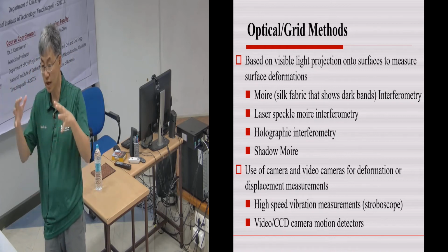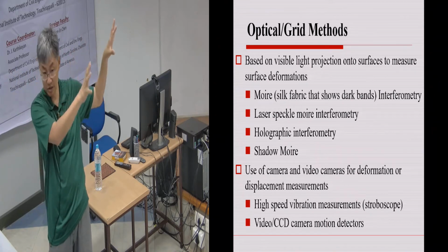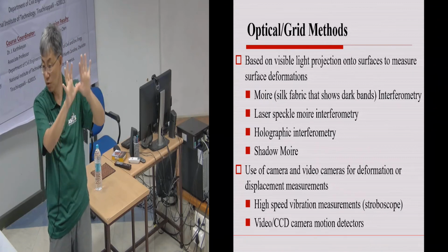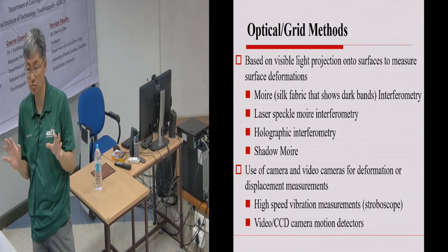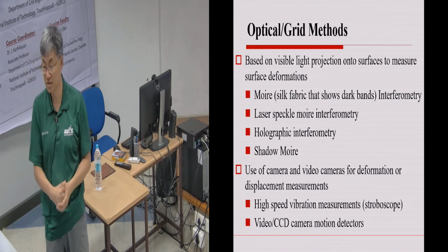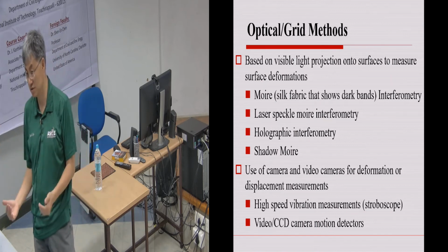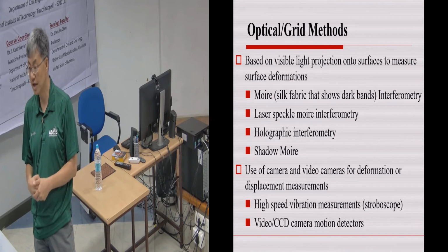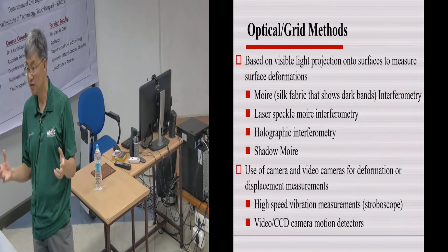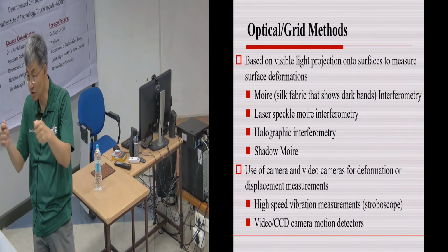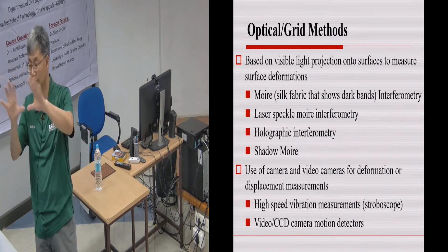Hologram is you create an artificial surface on a material, and then when the material starts changing, the hologram will be able to pinpoint what are those changes. All of these are deformation based, okay. But deformation is extremely important, right? Because as we discussed yesterday, we never measure force or stress. The only thing we measure in real life is deformation, okay. And optical methods also have another area of benefit, that is area, okay. The light shines on one area. So using ruler measurements, you have to measure many times, but light, it covers all, okay.